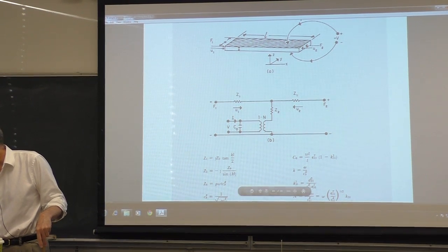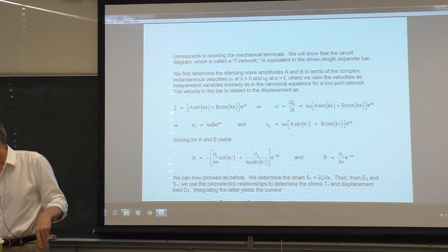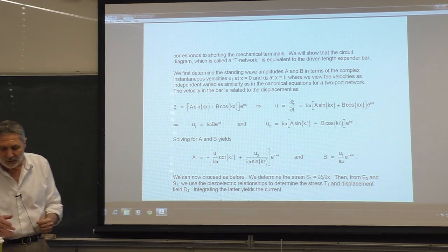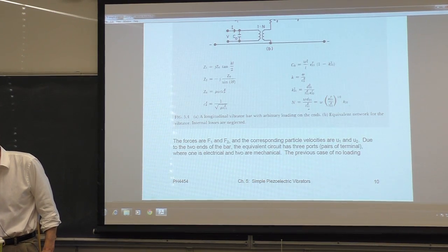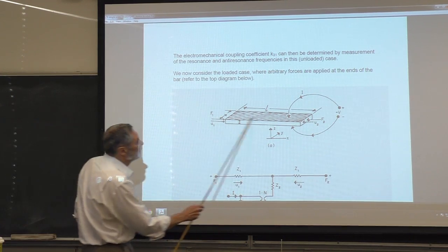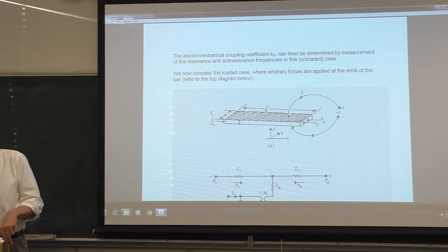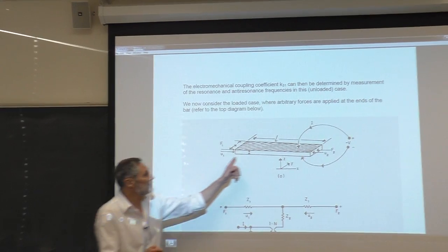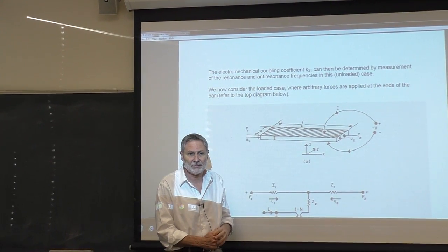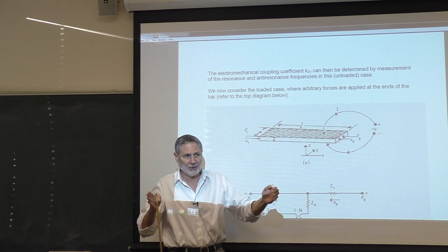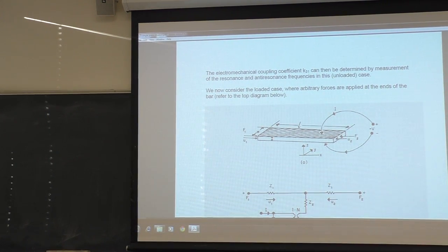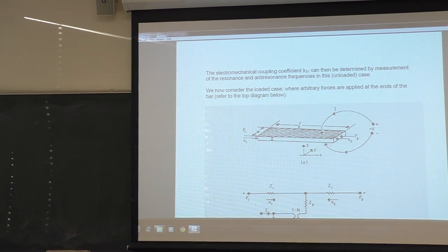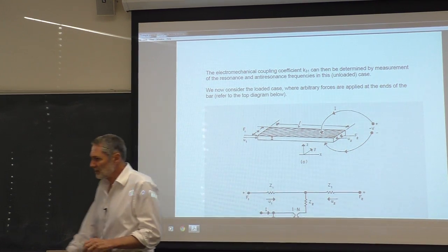So, how do we begin here? We begin with this longitudinal strain. That's the primary strain, the one we're interested in here, in the x direction, and we deal with that. And remember now, we generalized this before to include the possibility of standing waves in here. So we're not necessarily at a sufficiently low frequency that it's uniformly expanding and contracting. We can have standing waves in there. We're being more general. The uniform expansion and contraction is a special case. It's the low frequency limit of our theory here.